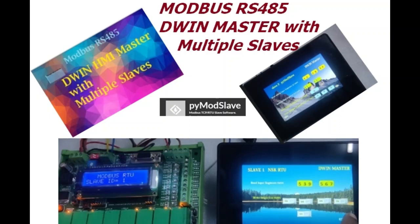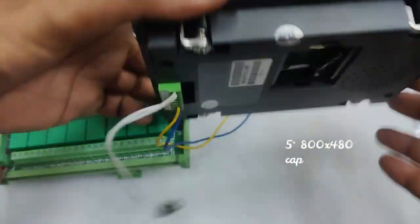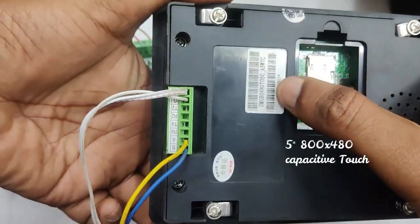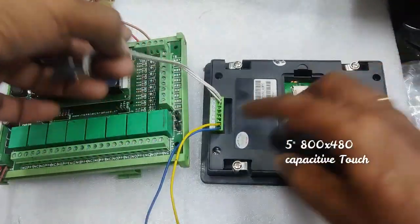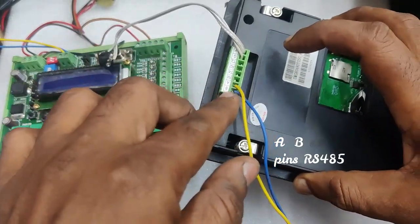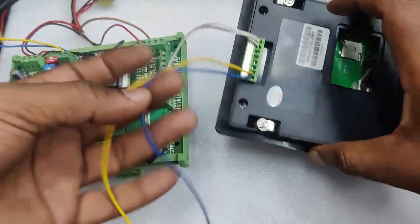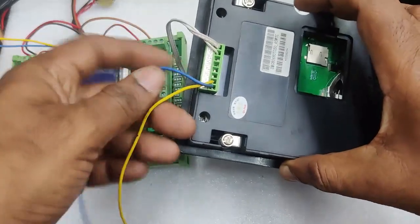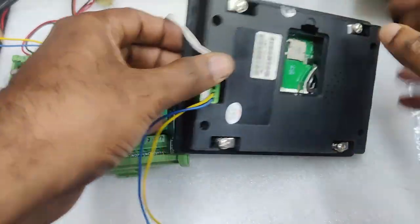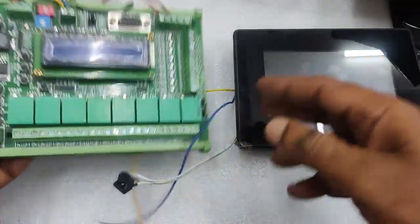Hello all, in this video we'll see how to handle multiple slaves with the DWIN master with the Modbus protocol over RS485. Here we have a 5-inch 800 by 480 industrial grade display with the casing. On the top are the 2 pins for power source. At the bottom we can see A and B pins for RS485. We'll be implementing Modbus protocol over RS485 with this display where DWIN is configured as master.